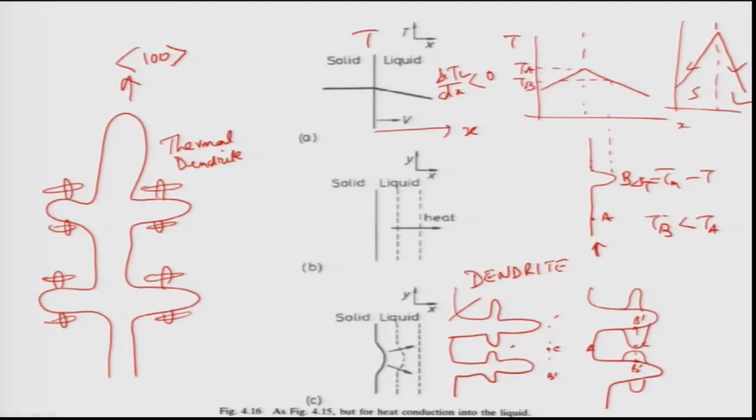For hexagonal crystals, these are <10-10> or <0001>, the two directions which have been found for an HCP crystal. On the other hand, <110> is found in tetragonal crystal. So for every crystal structure there are well defined growth directions normally observed when the dendrites grow.